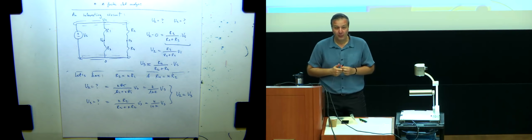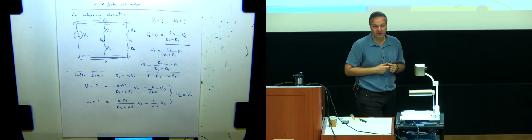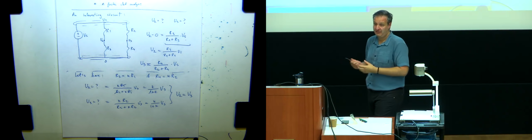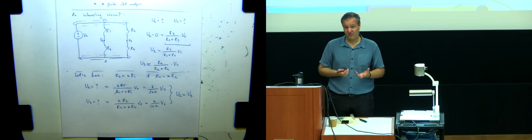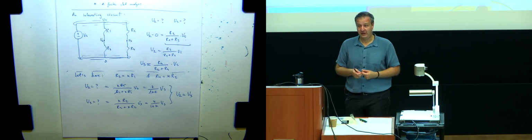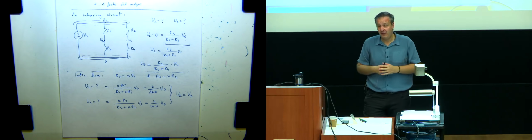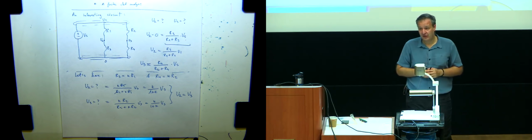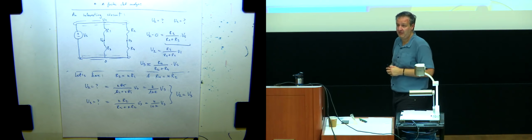If you pick a 1 ohm resistor from a 1 volt supply, that will be 1 watt. That's kind of hot, but it's okay. If I pick a 0.01 ohm resistor, that will be 100 watts.